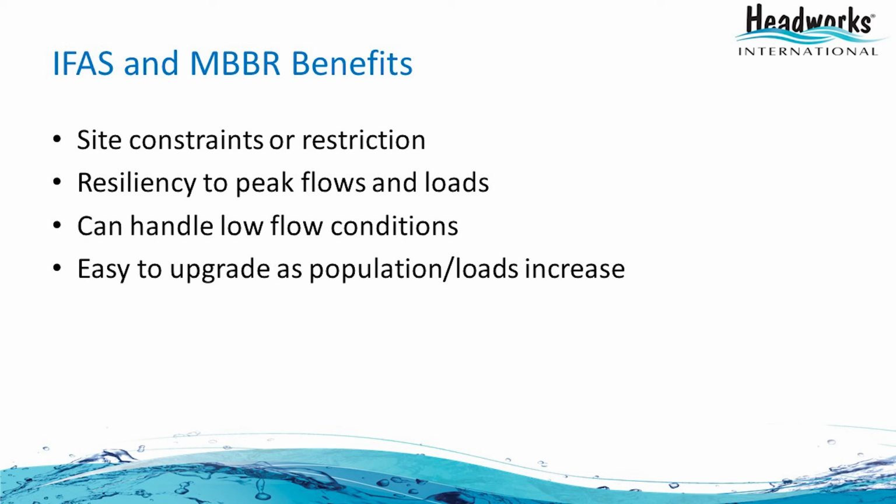If you have an activated sludge plant running at only 20-30% of the load, your suspended growth bacteria will die off. Whereas in MBBR and IFAS plants, the bacteria survive on the biofilm for as many as 3 to 7 days. So even after 7 days, the MBBR can come back to life really fast, because the biofilm is strongly attached to the media, and they survive using endogenous respiration and wait for the new load to come back. So when the new load comes, it will automatically grow and meet the new condition really fast, within a few hours. And it's easy to upgrade in a modular fashion.